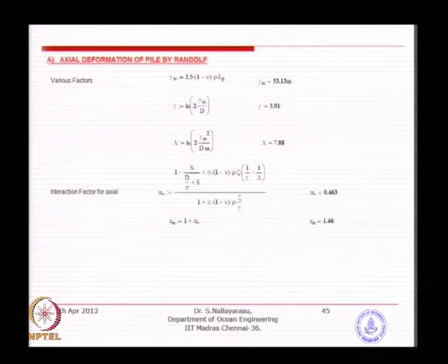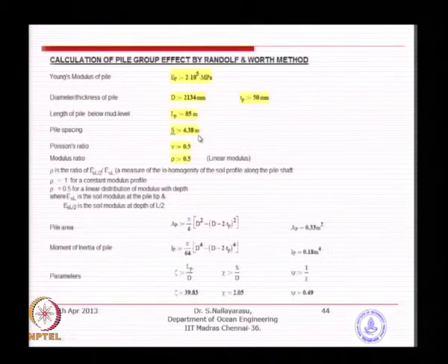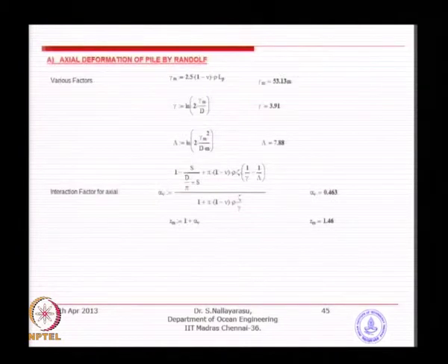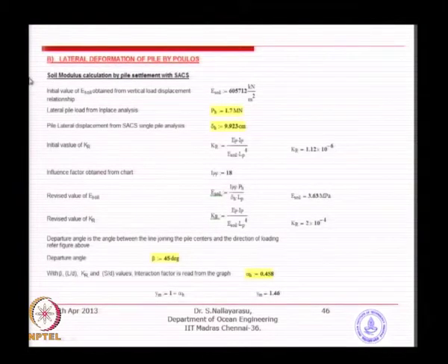So, that is why I just wanted to demonstrate that you can actually go back and calculate for 3 diameters, and you will find maybe 10%. If it is 4 diameters, probably you will not find any effect at all on the deflection, it will diminish. Whereas, if you look at the lateral deformation, this will be an even bigger effect depending on the type of soil.